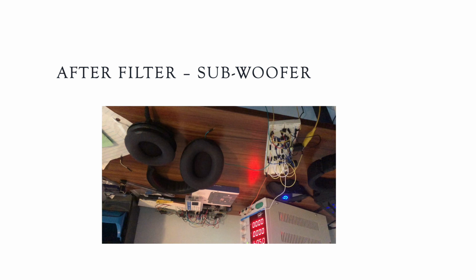You might notice that the vocals sound incredibly distorted, while the bass line can be heard loud and clear. This is because the vocals lie outside of the pass band of the filter, so they experience both a reduced gain and a distortion factor due to the phase shift.